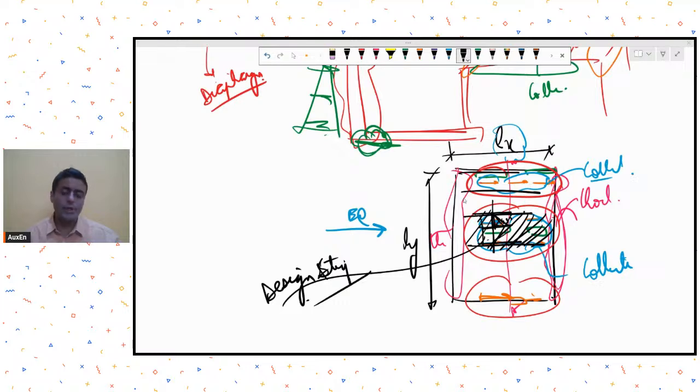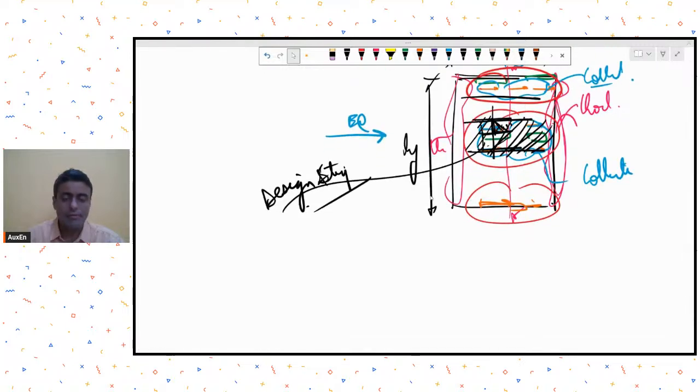So you need to be more careful about these zones, the chords and collectors, when it comes to design of slab for lateral forces. Usually we call it the design for diaphragm or diaphragm action. A very good document for this you can find on the internet. It is a document published by NEHRP.